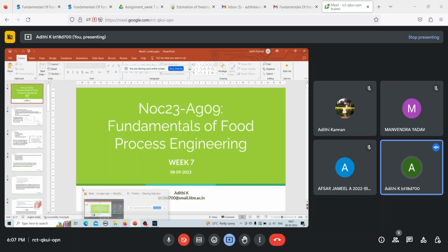P and R are constants that differ with the kind of geometry that we're dealing with. A cube will have different P and R values, a cylinder will have different ones, and spheres will have different ones. We'll discuss what P and R are for this particular question. A is the dimension of the potato cube, h is the convective heat transfer coefficient, and k is the thermal conductivity.